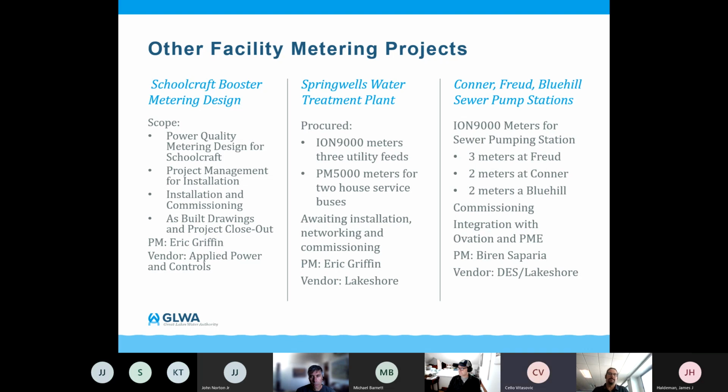And for the most part, we're focused on those major loads, the pumping units, but in some cases we're looking at doing smaller sub-metering too, just to understand our energy usage. In some ways, that's our biggest opportunity for energy efficiency, smaller loads, because it's difficult to reduce the power consumption on our large pumps without major CIP work.